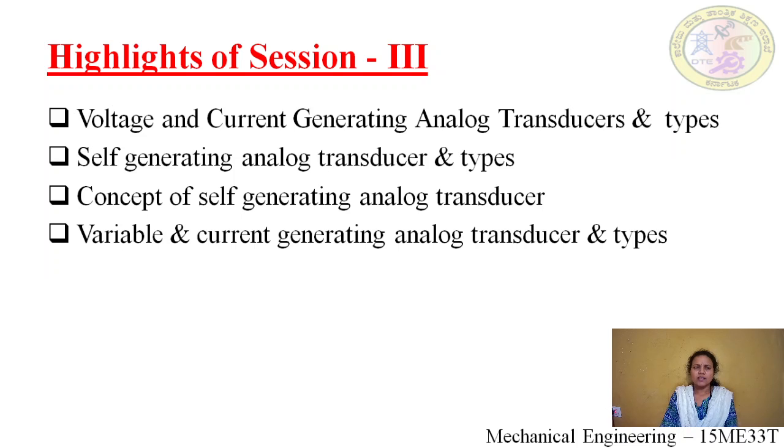These are the types of transducers in which the input variation is converted into a variation in capacitance, resistance or inductance, which in turn is converted into voltage. For this conversion we used an external power source.